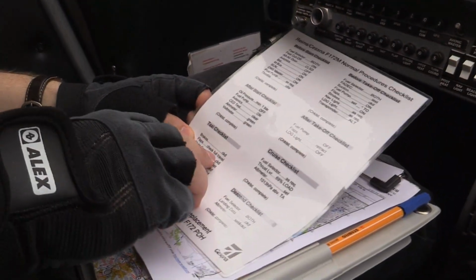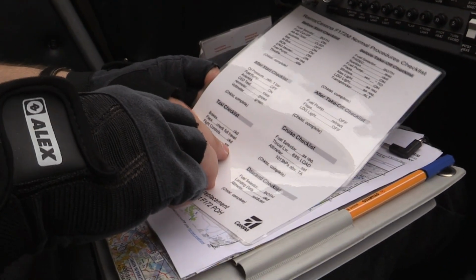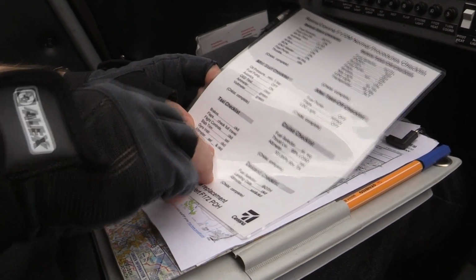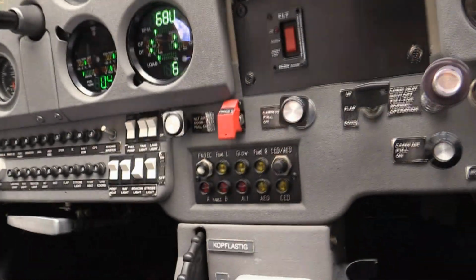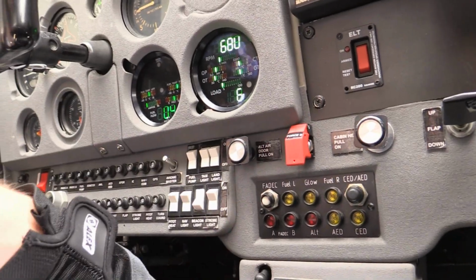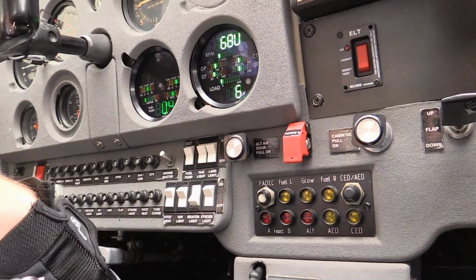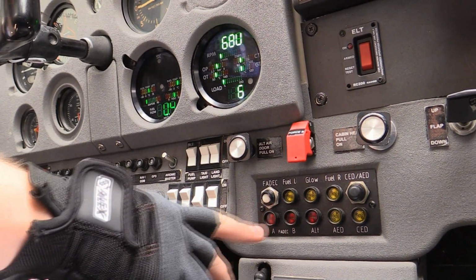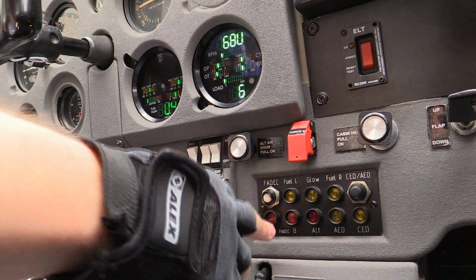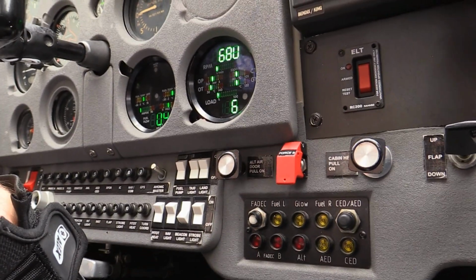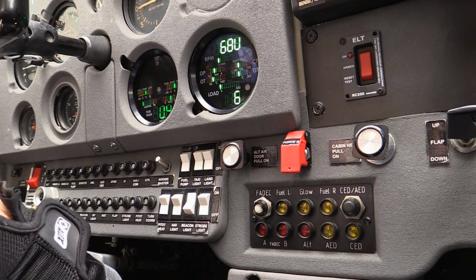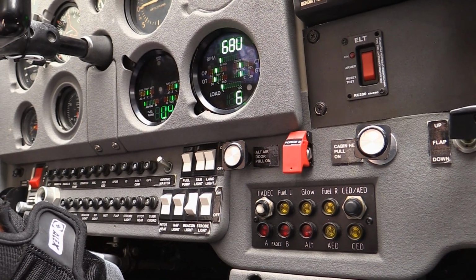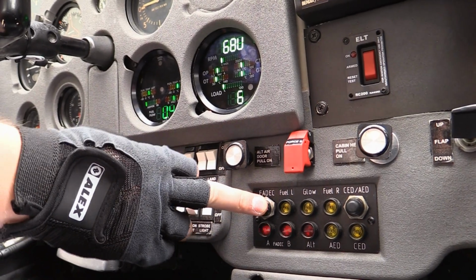We checked our brakes, flaps are checked for full travel, flight controls were checked, trim is set, gyro instruments are checked, and the altimeter is set and checked. Alright, now for the run-up, I just press this button. The FADEC will spool the engine up to 1200 RPM approximately, and then switch off one of the two control units. Adjust the propeller pitch, see that the governor is working, then spool down to 800 RPM for idle, and switch to the other control unit and repeat all that again. So let's see how it goes.